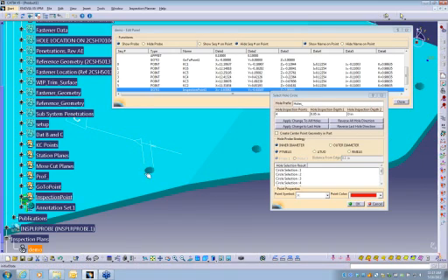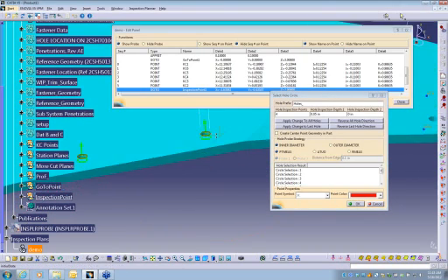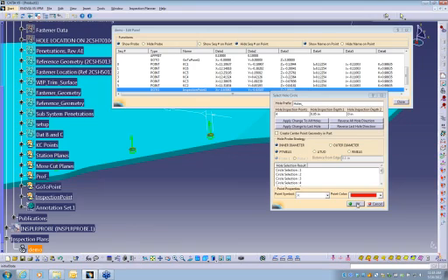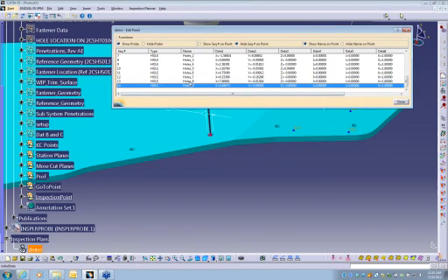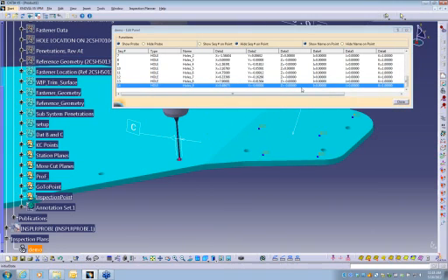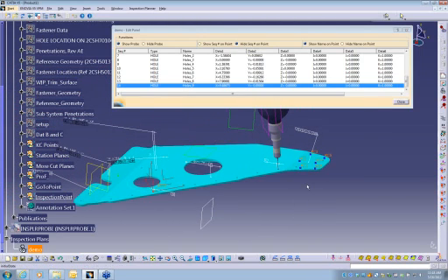You just kind of have to hover over the hole. Now we're going to reverse all the holes. And what we're seeing here is there's our 50 thousandths, so we're going down in the hole, and we're going to keep these red. We'll say OK. So all the holes are programmed. We're getting the XYZ, IJK, the diameter of the hole, all the information to run this part.